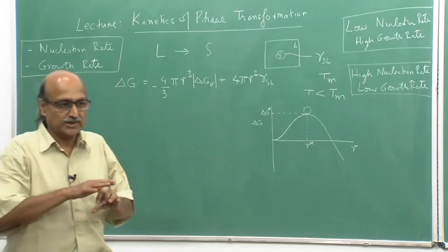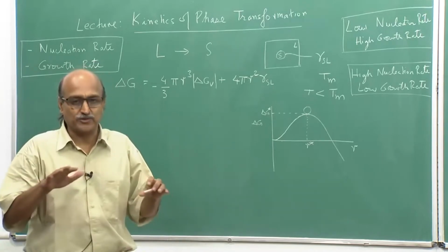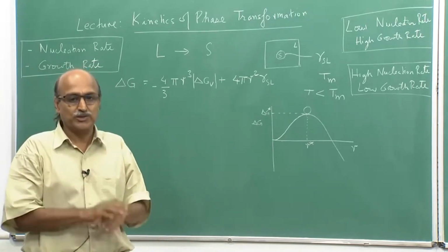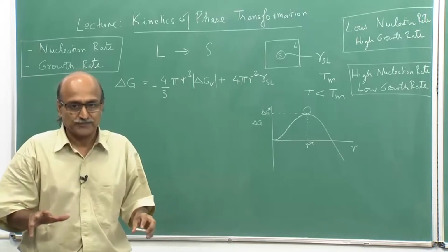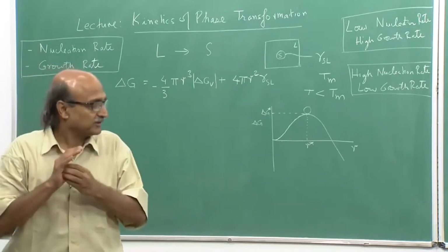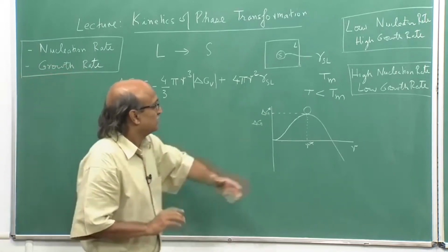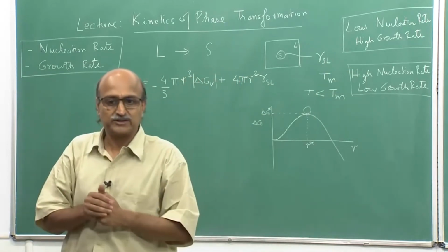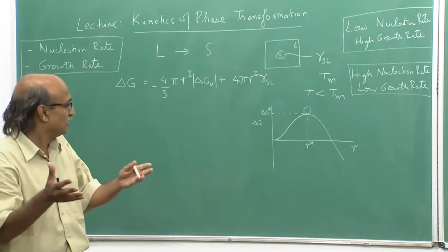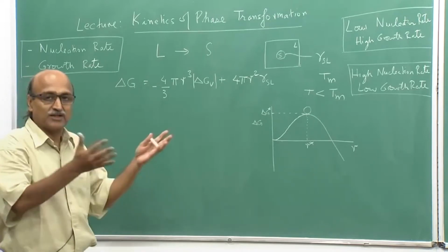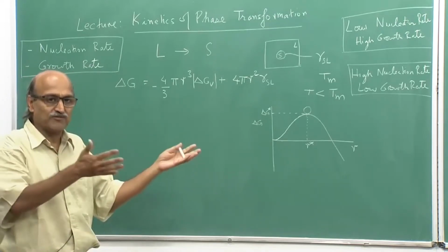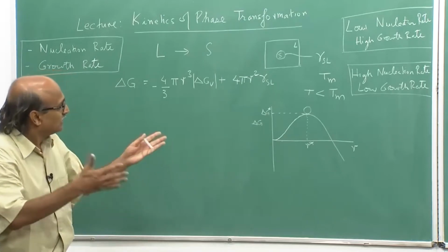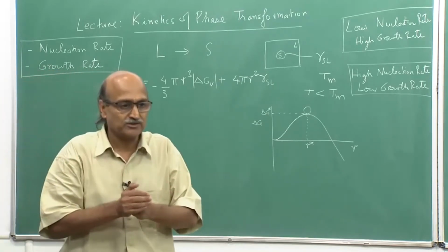What is the size of the grains or the size of the particles that are eventually produced? And in fact, if these conditions determine the scale of the microstructure, then in turn a material in which you have, let us say, large grains has a different set of mechanical properties versus a material with small grains.